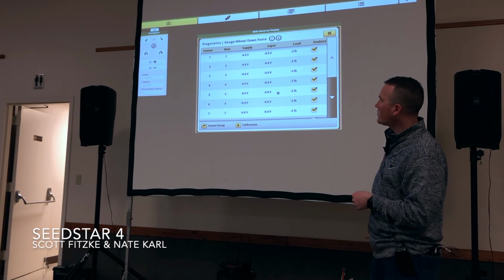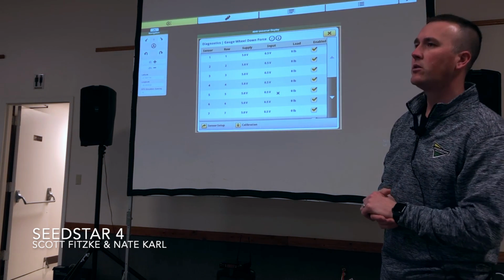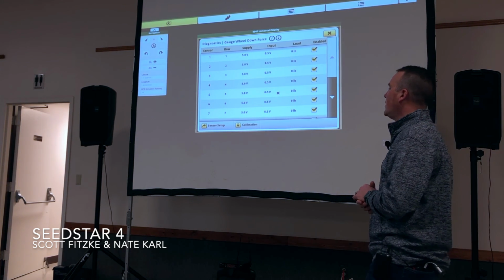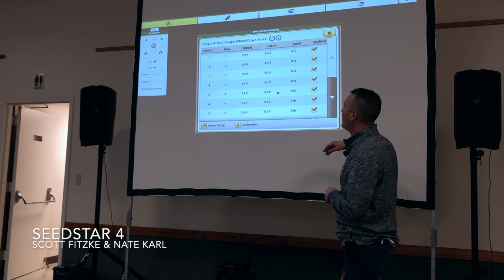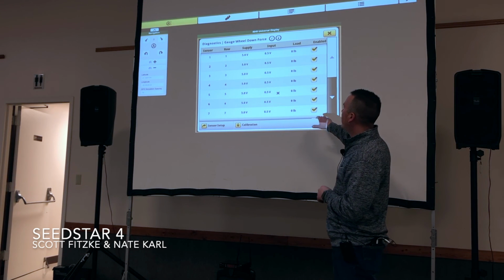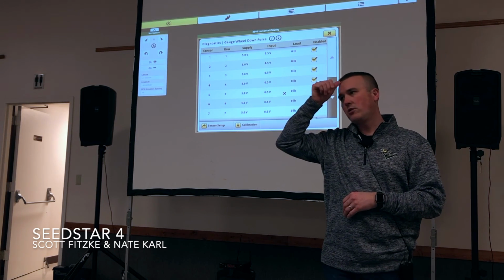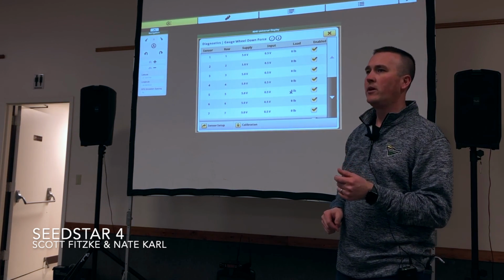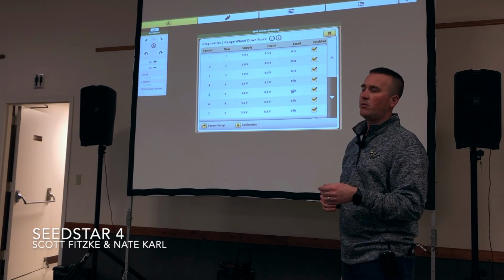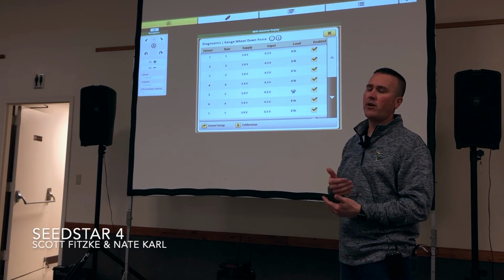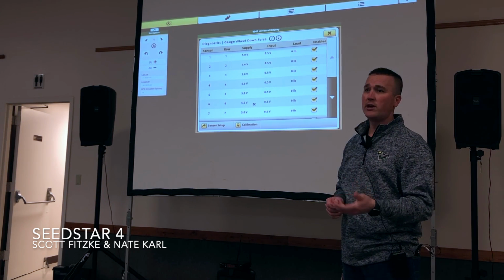So from here, we're really starting to dive into diagnostics to help us troubleshoot something on the planter. If we have an issue going on and we want to look further into it, we can use this to help guide us along the way. More importantly, because we've got a load cell in this planter on every single row, we want to make sure that those load cells are performing properly, since that's really going to determine our adjustments as far as how much weight we're applying with those hydraulic cylinders, and ultimately that's what's going to determine if we've got that row unit at depth.